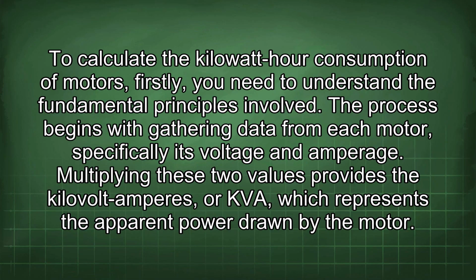To calculate the kilowatt-hour consumption of motors, firstly, you need to understand the fundamental principles involved. The process begins with gathering data from each motor, specifically its voltage and amperage. Multiplying these two values provides the kilovolt amperes, or kVA, which represents the apparent power drawn by the motor.